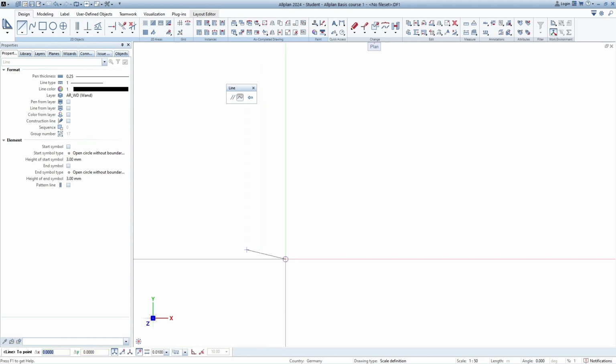And now we have the 2 point. So line 2 point, and now we can input coordinates. So we have delta X and delta Y. If we input a delta X coordinate, the grid from the coordinate input will start at the first point that we have defined. So if I input the value 5, the following happens.